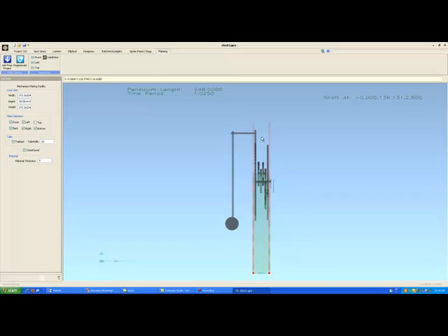And we're probably a little tight because I don't allow clearances when we do this. So you can just go up to the depth box, and I'll enter a 45 here and hit return, and then regenerate. When I hit regenerate, the box is now wider, and we have a bit more flexibility in how we fit it. You can make that as wide as you want. For an example, let's do 55. Hit enter, and you can see that the box gets bigger.